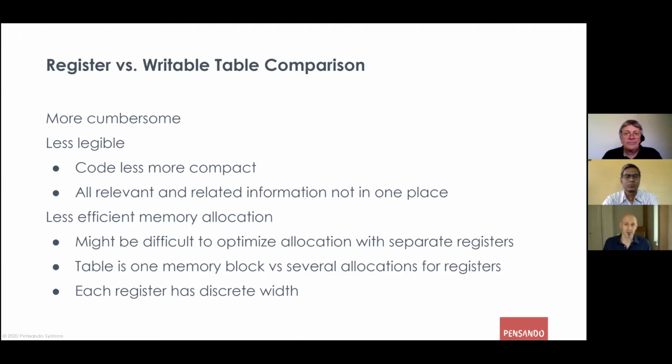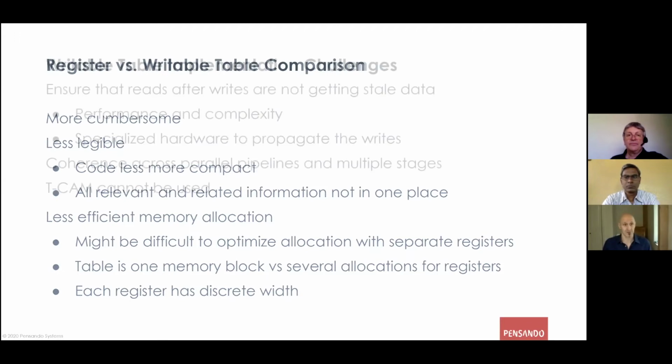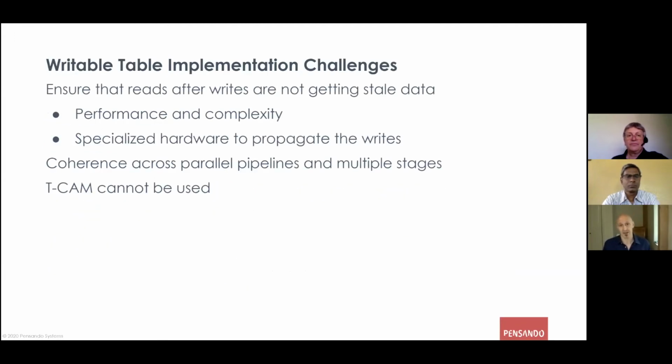Especially the separate registers, each one has a discrete width, which we might not be able to exploit. It also has a limitation on the depth, and so we might not be able to use them efficiently. On the other hand, of course, having writable tables comes at a cost, because we have a number of challenges. First of all, we have to ensure that reads that come after writes get the right data, the data after it was modified. And this is not easy to handle.